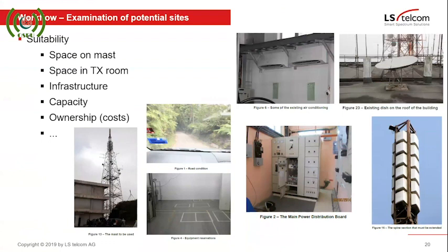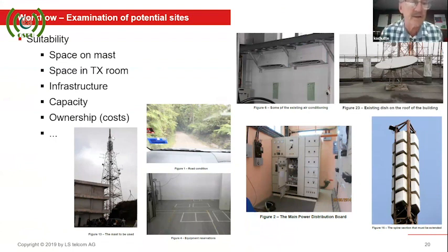So if we look at that, then obviously we need to look at the space on the mast. Is there space for an additional antenna if you have not been using, say, UHF on the mast, and you have got a VHF section and maybe some FM antennas below, but you don't have enough space for a 4-stack and 4-bay panel antenna system.